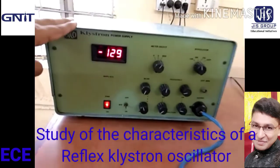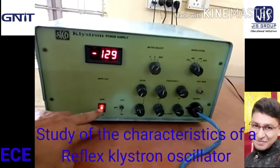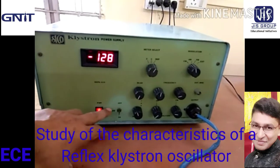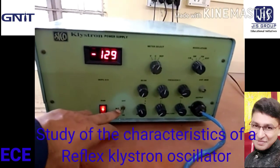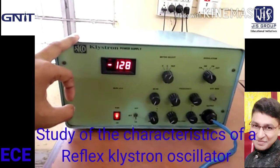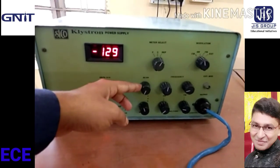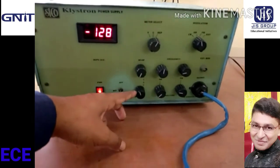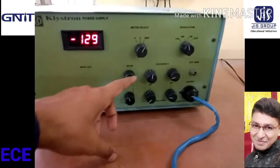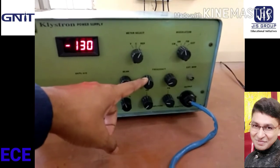This is our klystron power supply. This is the power switch. This is the AST switch. When AST is on, the power supply produces the electron beam. This knob varies the beam voltage and beam current. This varies the repeller voltage. This varies the frequency for amplitude modulation.